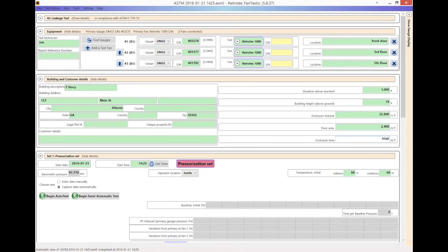One of the things that I didn't have, I have slides to do this, but I thought I'd talk about the software first, was that you can do air changes per hour, which is very common, and many of the folks that are out there are used to doing air changes per hour when they do a blower door test. You can also do more of a commercial style, which is surface area, which is all 6 sides of the box, and how much leakage I have per square foot. So there's different ways that it can do it, and this can do all of them together, but it needs some of the information that's on there.